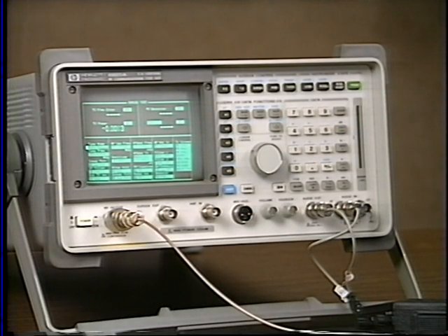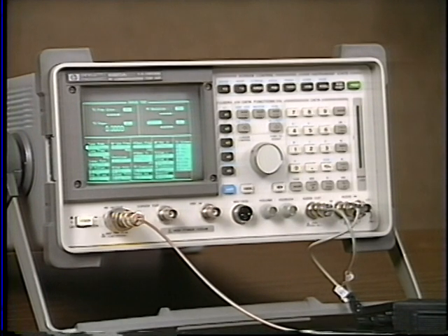Another time saver that you can take advantage of is coupling between signal generator and the tuning frequencies. In many radio systems, the duplex radios have a fixed offset, for example, in the cellular radio band 45 megahertz. The 8920's generator and receiver can be set up to automatically track in frequency. As you change one, the other will automatically change with you.